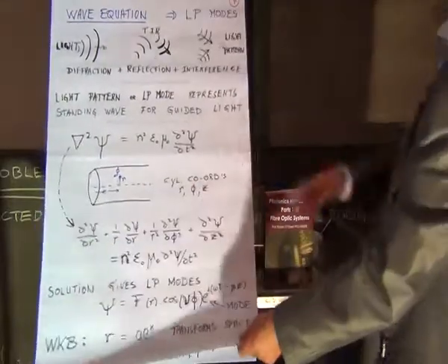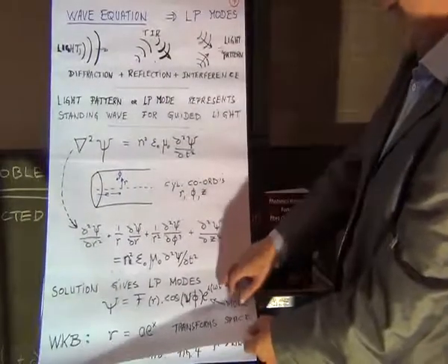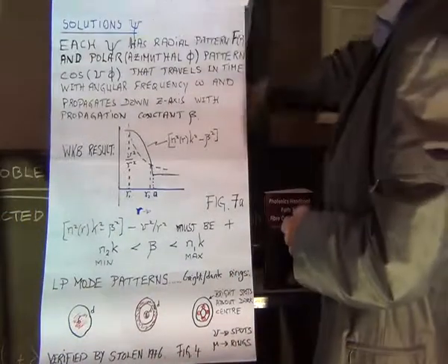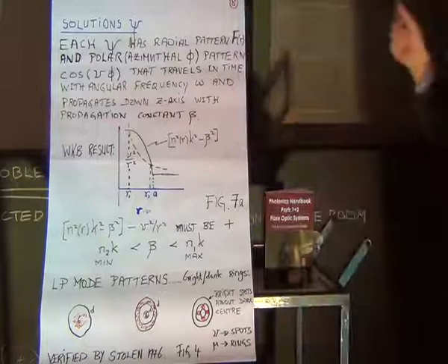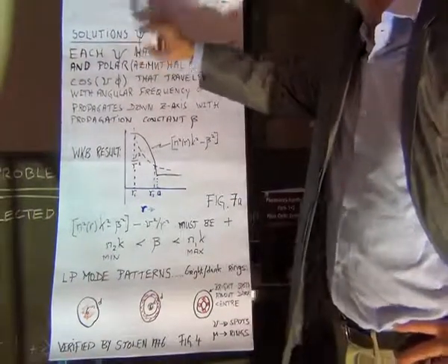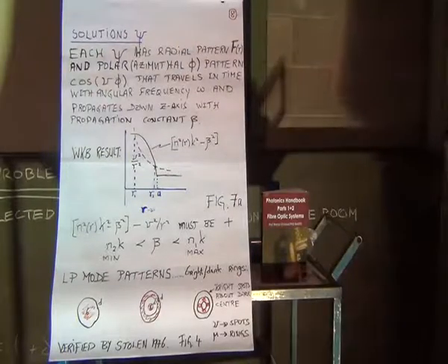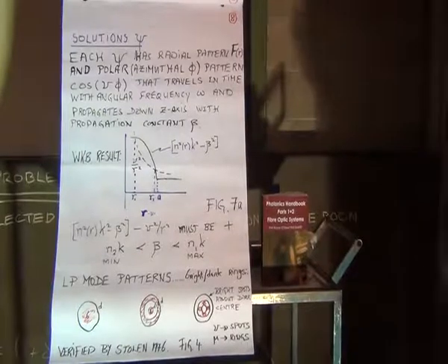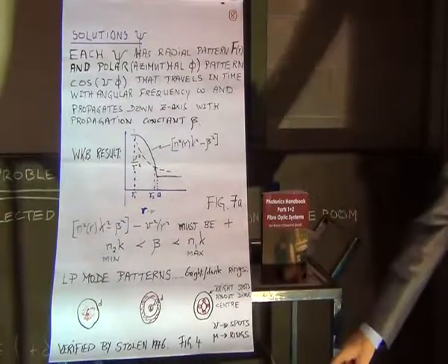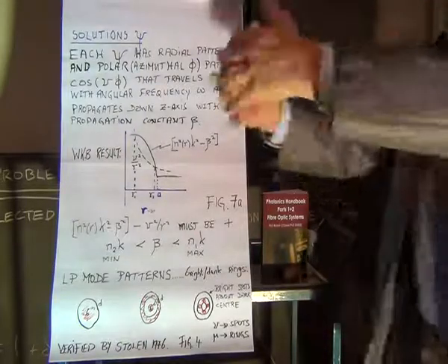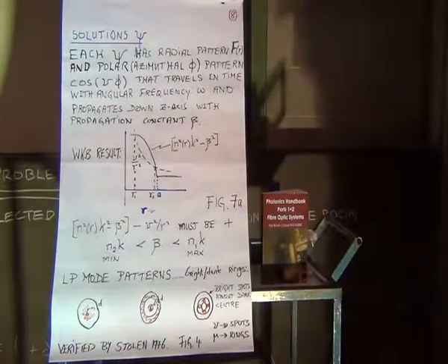All right, that double differentiation brings out these things, beta squared and all of the rest. And it turns out that all the solutions for the optical field psi, which we call the modes of the fibre, are the guided patterns. These are standing wave patterns just like on my board there. Okay? And they travel down the fibre at the rate beta, which we're looking for.